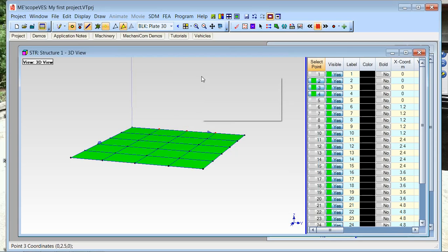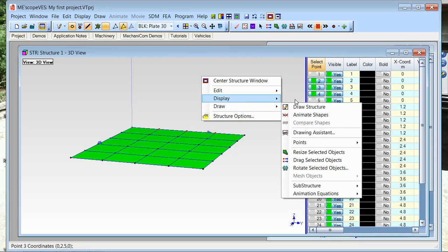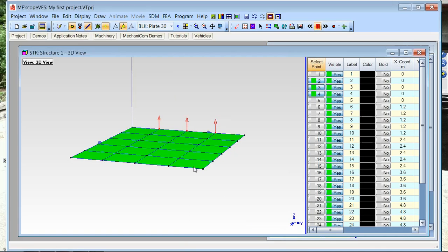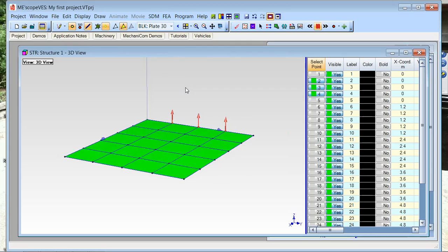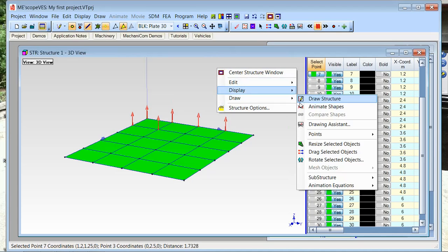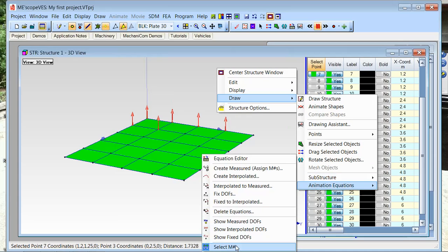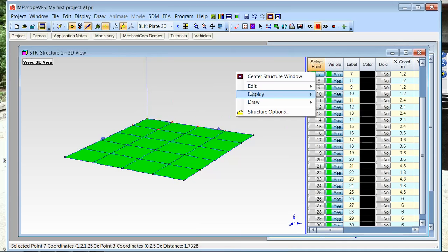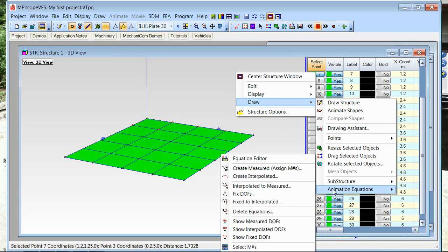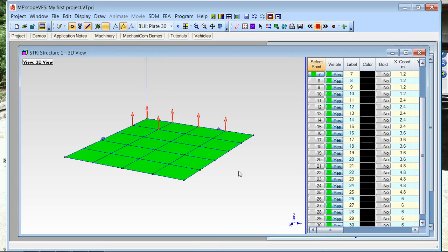Now this won't always occur. If I go back to the line cursor and just put the line cursor in my data, there's an ODS. That ODS is a combination of contributions from all of the surrounding modes. So the best assumption you can make when you're looking at ODS is that all the modes are being excited at all frequencies, but depending on their mode shapes, certain ones will dominate, and also depending on where the forces come into the structure.